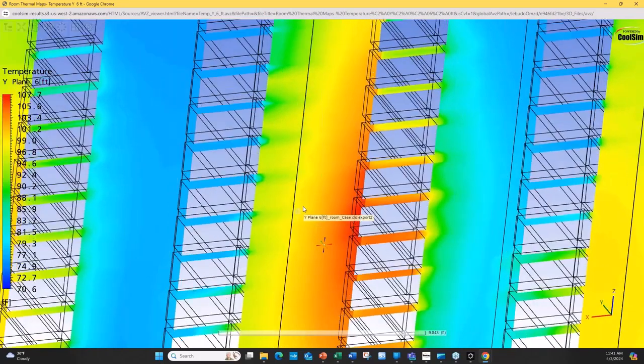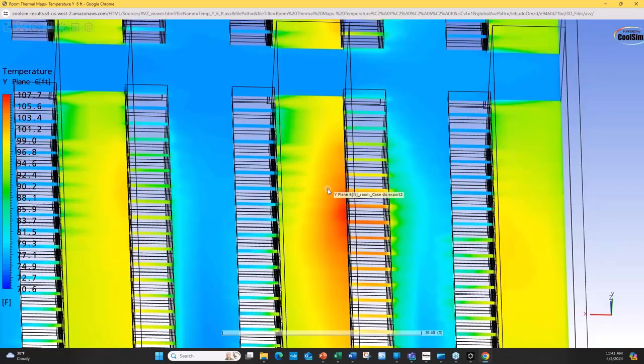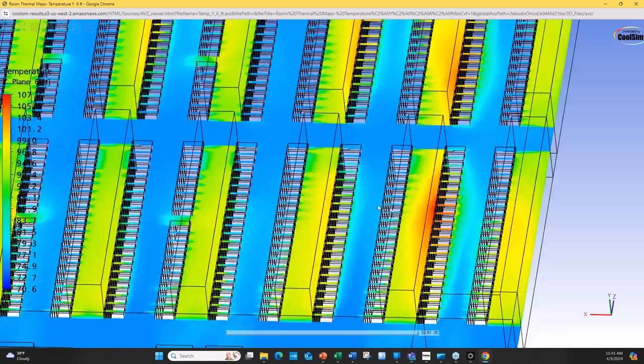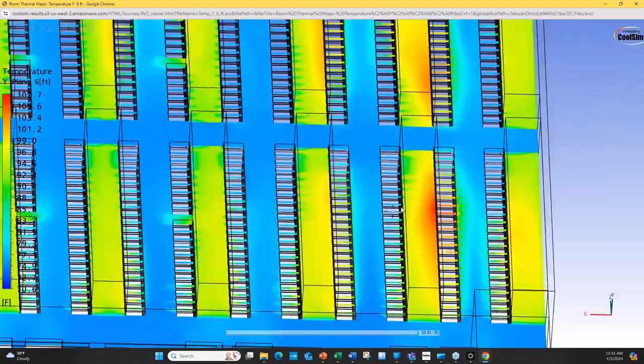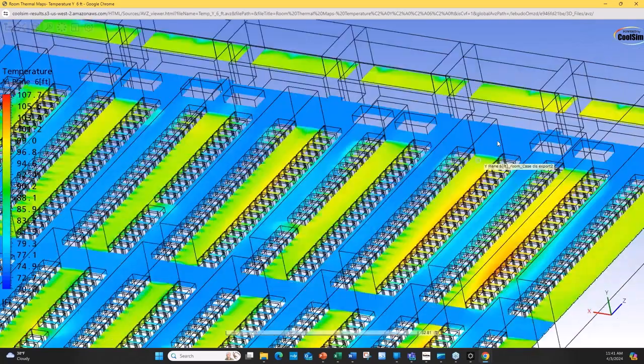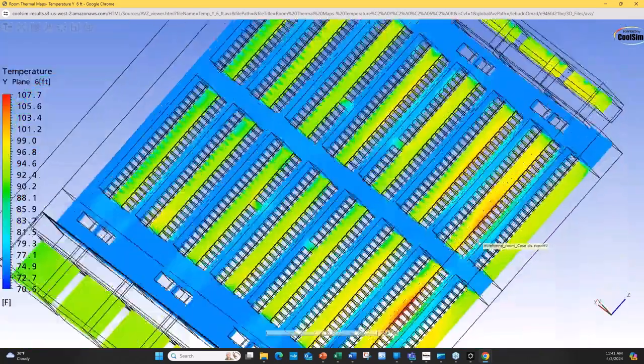So I think, Paul, that this demonstrates the importance of air management, because this is nothing else than an air management issue. You haven't tightened up your equipment rows. So what we are preaching in our training program is air management is a prerequisite before you do other energy efficiency measures in data centers.